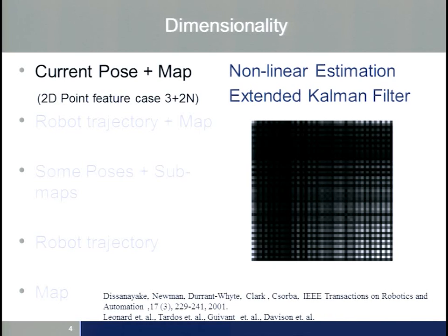When you look at the covariance matrix of the state estimate, it becomes gradually denser and denser, and that turns out to be quite a problem, because the way to solve the problem is to invert this matrix, and that requires quite a bit of computation. It also turns out that these cross-correlations that get built up as the map evolves are critical to the problem, and that's the kind of thing that makes things like your loop closures work. So you can't basically get rid of them.